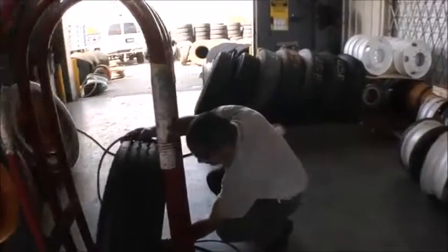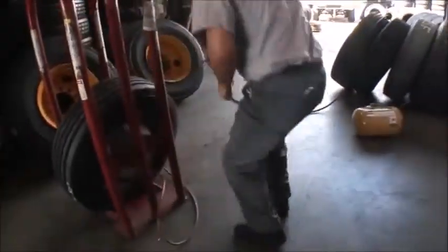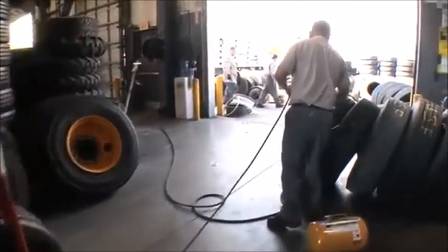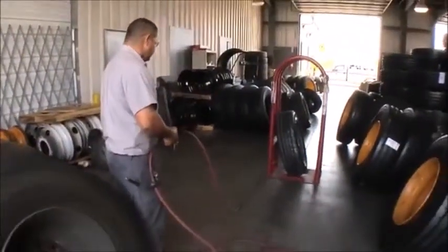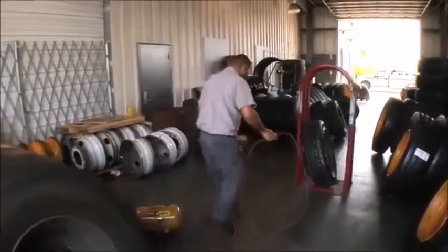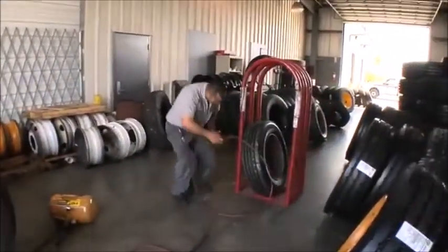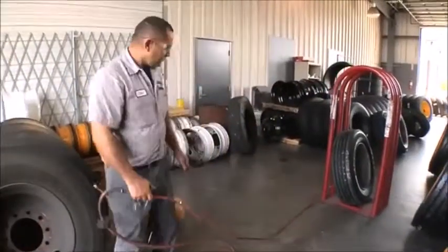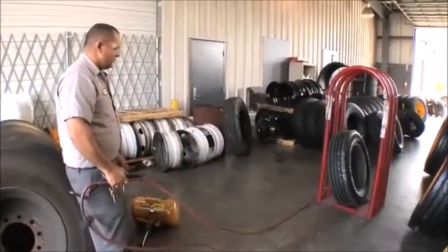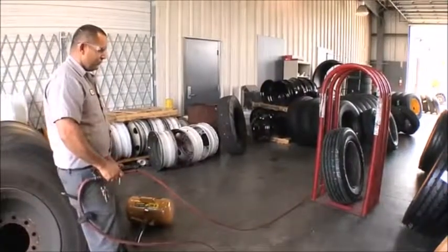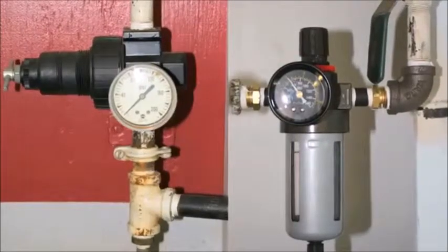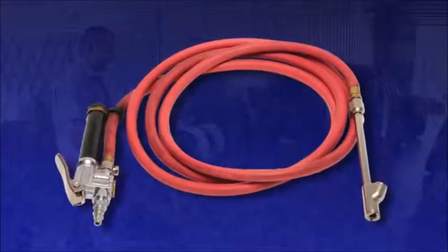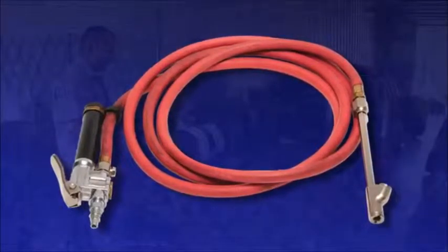The first component that must be in place is a clip-on air chuck. This allows the technician to temporarily attach the air chuck to the valve stem and inflate the tire without the need to stand directly in front of the sidewall. The second component is a sufficient length of hose that allows the employee to stand outside the trajectory during the inflation and inspection process. Finally, all truck tire inflation devices must include an inline valve with a pressure gauge or a presettable regulator. Both are designed to prevent accidental overinflation and should allow the technician to deflate the tire without approaching the assembly in the restraining device.